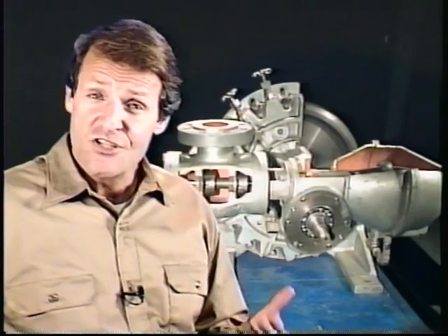If the trip latch is okay, but the turbine is tripping too soon or too late, the overspeed setting may be incorrect, or the cause of the trouble may be in the trip pin assembly. In either case, you should let your supervisor know about the situation so it can be checked out and corrected. Also, let your supervisor know if the overspeed is tripping, but it isn't stopping the turbine. That could mean there's a problem with the overspeed trip valve, and the turbine may have to be shut down so repairs can be made.